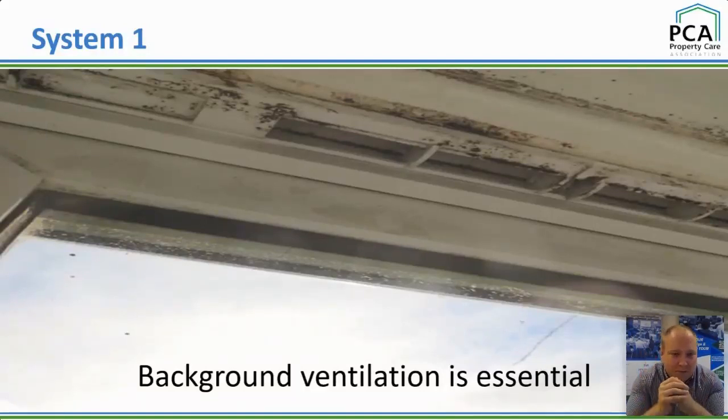Normally you'll find them above the windows. But if they're retrofitted, another word to the wise: actually check that they've gone through. I've had a couple of people tell me that they've seen them literally just screwed onto a window casing, and there is no actual ventilation through the window, and they serve no purpose. So you should also be checking the output on each of those. There should be a number on there that gives you the output.